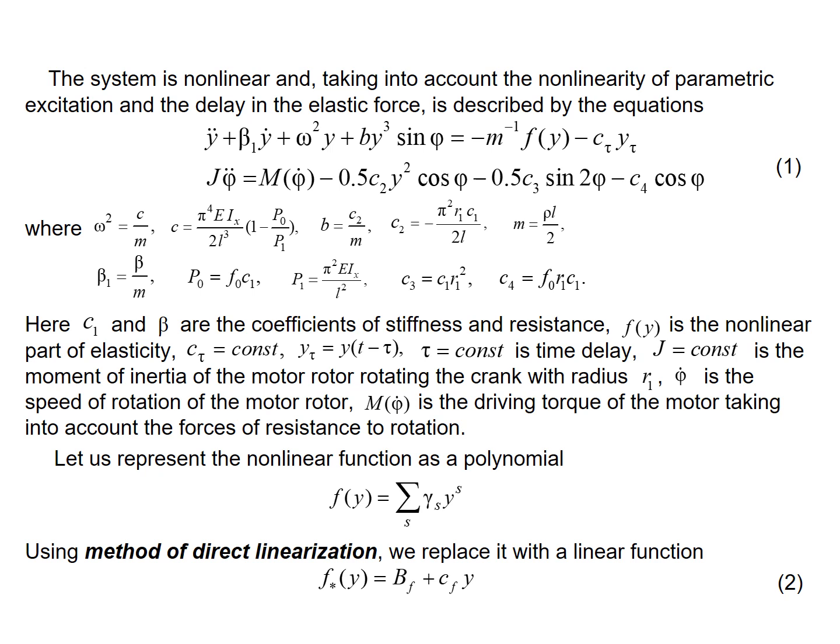Here, the symbols denote the coefficients of stiffness and resistance, and the nonlinear part of elasticity; the time delay; the moment of inertia of the motor rotor rotating the crank with a given radius; the speed of rotation of the motor rotor; and the driving torque of the motor, taking into account the forces of resistance